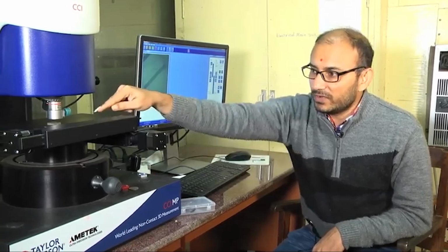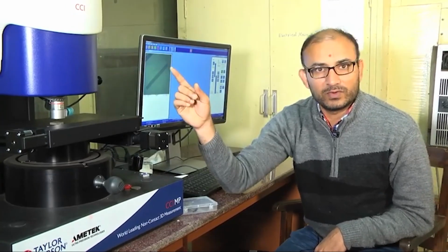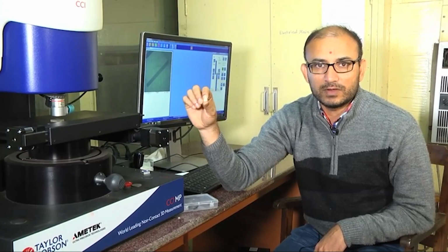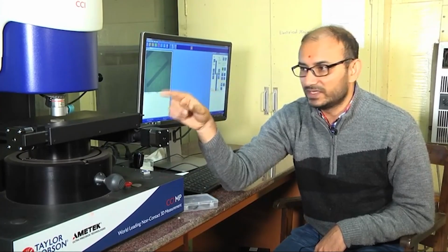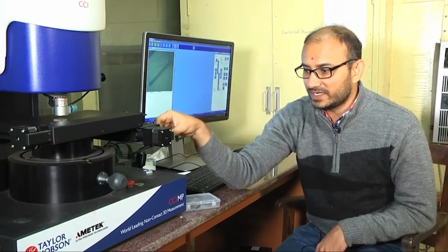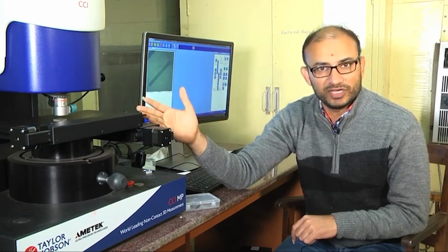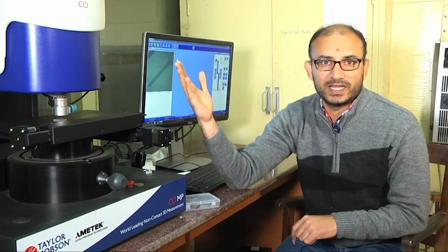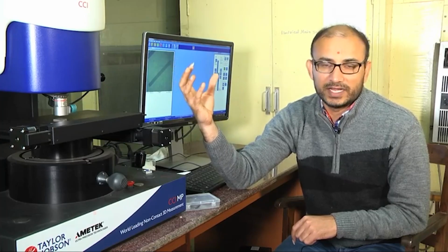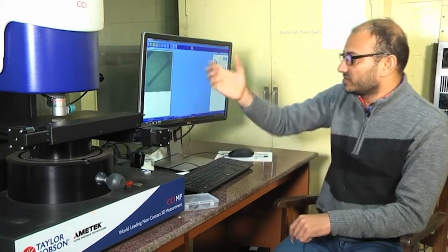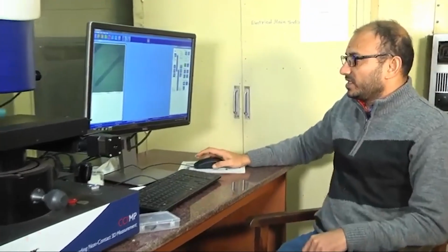Here, from the fabricated micro tool, we have cut one micro channel with a depth of around 300 micron, and the channel width we will measure by this particular instrument. Once you complete the measurement, you will understand that it is very difficult to see by naked eye what dimensions are fabricated. This is the 3D measurement. There is another one, called scanning electron microscopy, by which you can get 3D measurement with a higher depth of focus. So let us go to the machine screen.